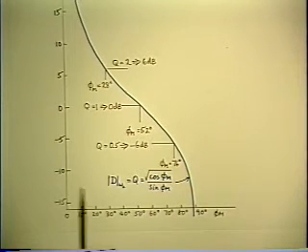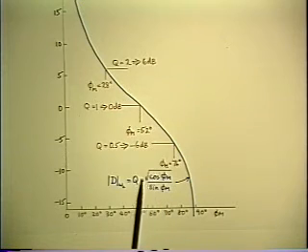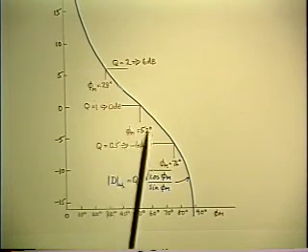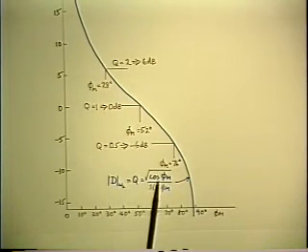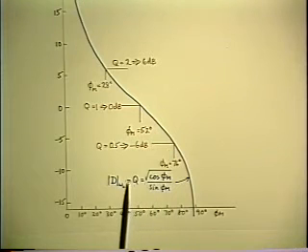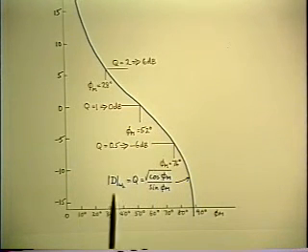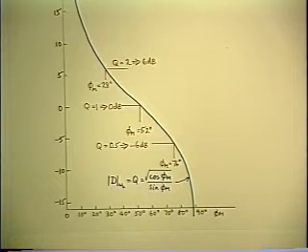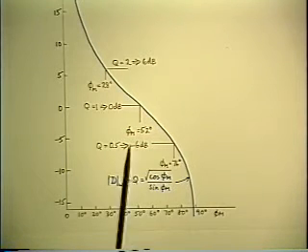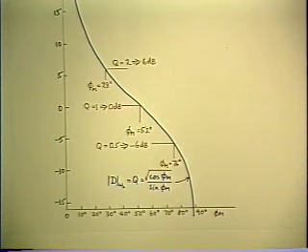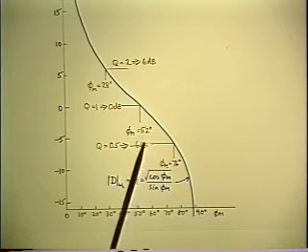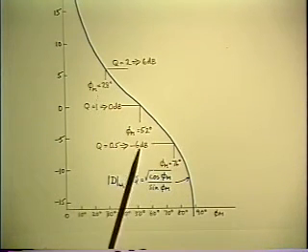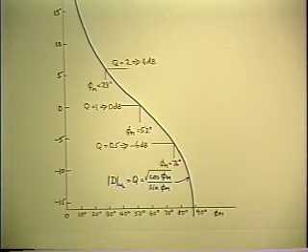This is a very interesting graph, because it gives you a quantitative idea of what a certain phase margin number really means. So the number of degrees means nothing in itself. What matters is the degree of peaking you're going to get in your closed loop response.